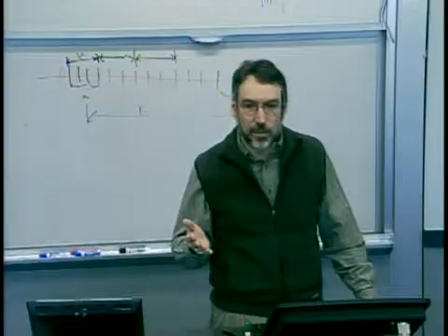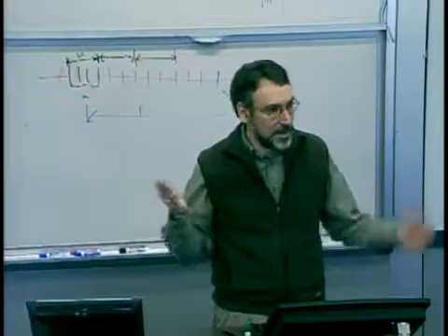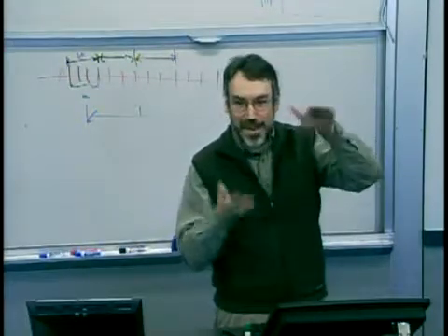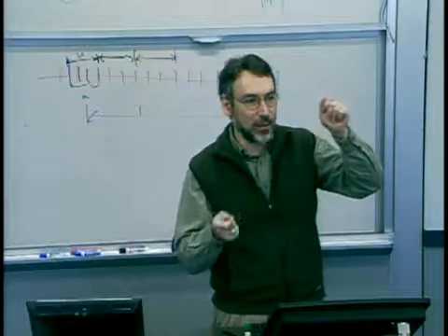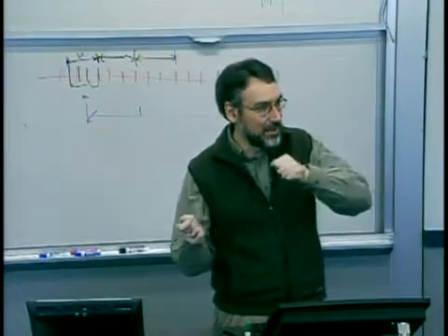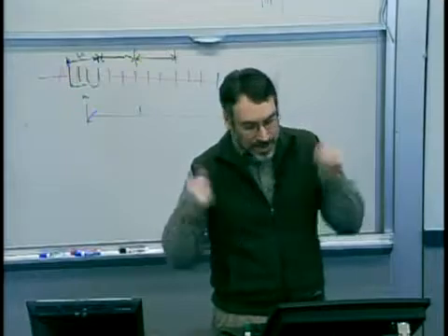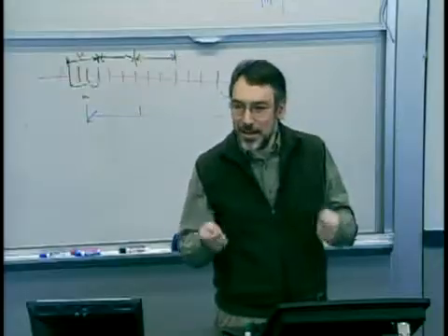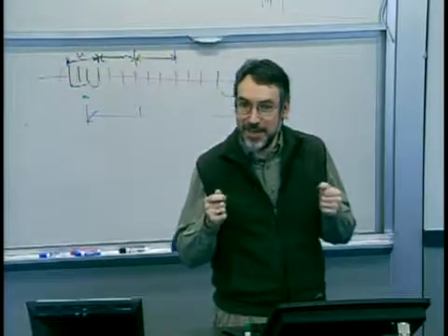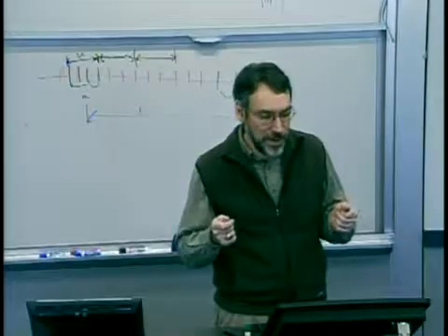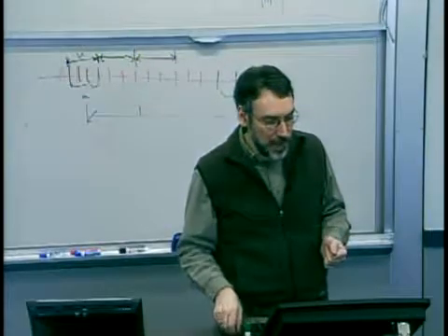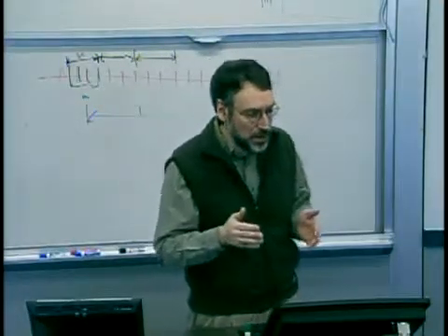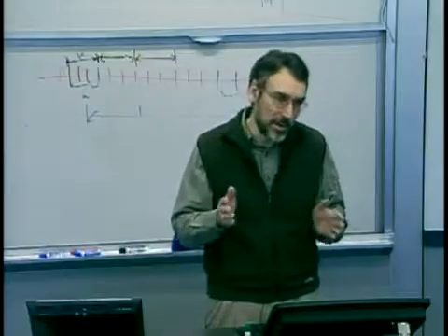When that's the case for a normally distributed process, it's characterized entirely by mean and variance, or on our control chart by X bar and S. So indeed, if the control limits have been set correctly in relation to known sample sizes and known probabilities of error and so on, then X bar and S tells you everything about the underlying process mean and variance, right? And now we can start to use those to look at where the process sits and those statistics sit with respect to tolerances or quality loss functions.